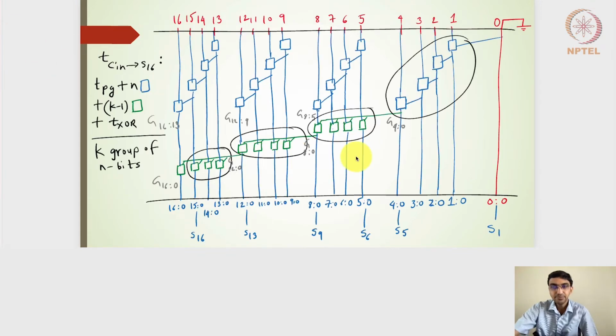So this is the PG level diagram which we had seen in the previous lecture. I'll take my pointer, and this first 4 bits are nothing but the carry ripple addition so as to generate G4:0. Then, as we said, it will generate 8:5, 7:5, 6:5, and of course 5:5. It is all going to wait for G4:0.